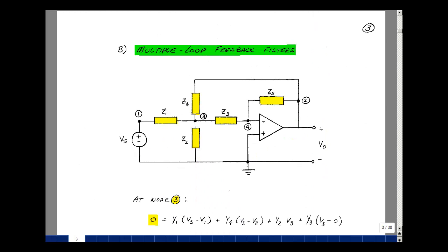What kind of a circuit could make this bandpass function? Well, in the ECE 202 notes, we showed that you could use an RLC circuit to do that. The problem with an audio circuit is that we're going to use a power supply that's going to derive its voltage from the wall outlet.